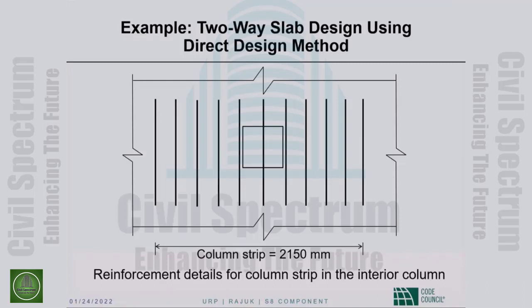You have to have steel shapes built into your slab that go around the steel column. All of this is provided for in ACI 318, and I suppose it is reproduced in BNBC. I do not know, but there are provisions. Look for lift slab construction and shear heads. Those are the key terms that you have to look for, and then you will see that there are provisions allowing this to happen.